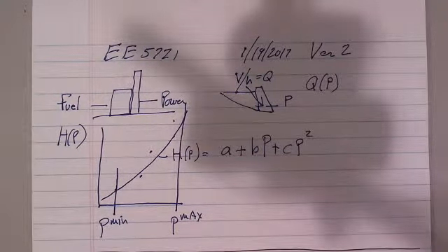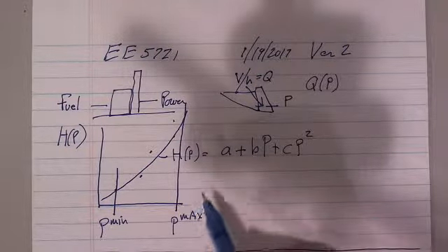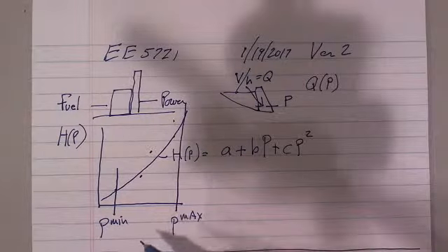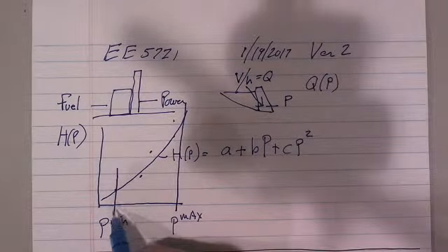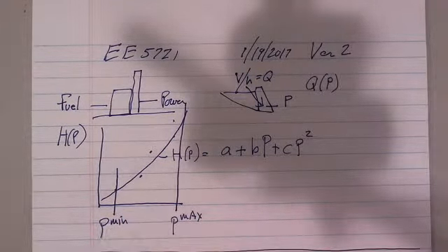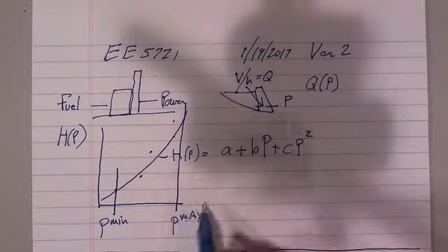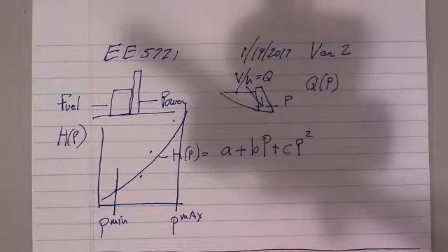So they like to get a power plant online, which means, again, that it is synchronized to the power system. The breakers are closed, it's synchronized, and they get it up to some place within P min, P max. But they don't operate it down here, and they can't operate it above P max because the mechanical side simply can't push it any further.